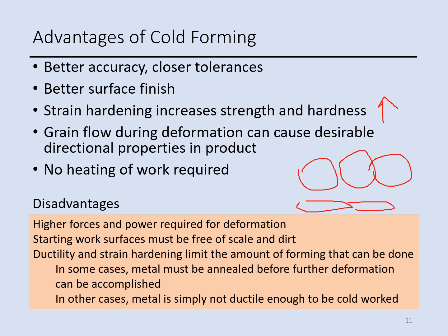If you apply a rolling process, apply force up and down, these grains are squeezed down. What happens, the grains become smaller in one direction, so you have some anisotropic property. So that's why it's called directional property.